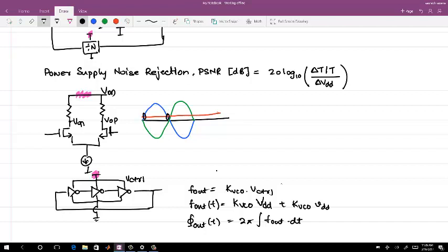So what you will not see is any change in the swing itself. The problem will be if one resistance changes differently with respect to the other, right? Then you convert into a differential mode. Common mode noise gets converted to differential mode, and that actually happens because you want to control this resistor with some MOSFET resistance or some different kinds of cells, right?